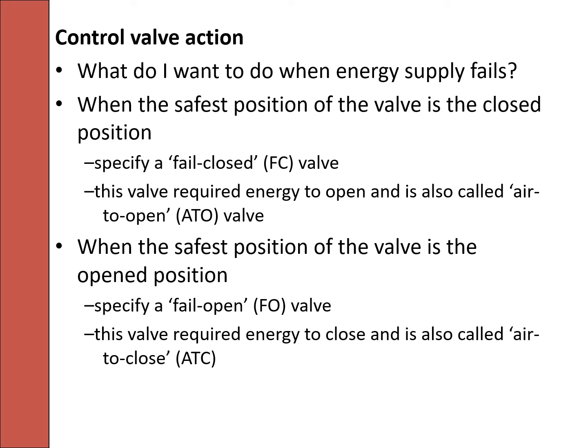This valve basically requires energy to open, and we also call it air to open. Like I mentioned before, normally we use air pressure to operate the valve. For this one, we need air to open the valve. When the energy supply fails, there is no air supply, so the valve becomes fail closed. The valve will not open, it will close.